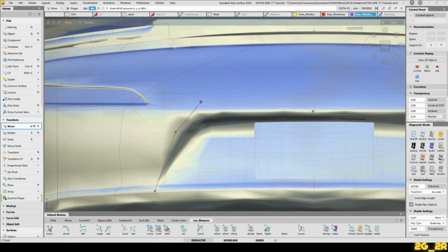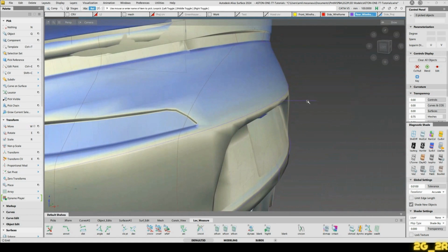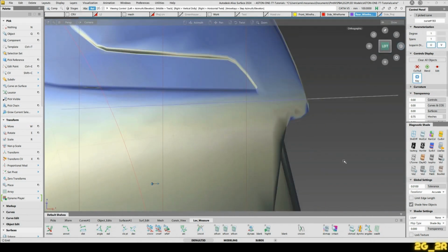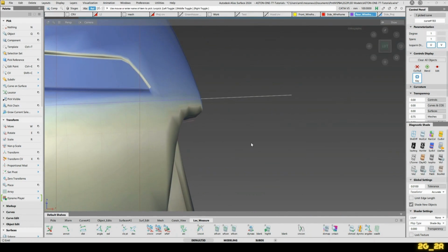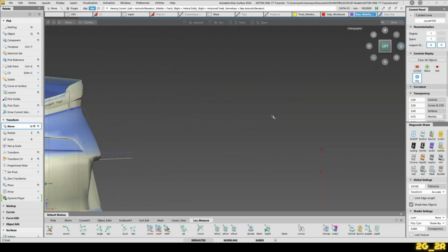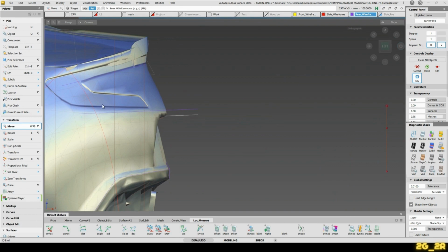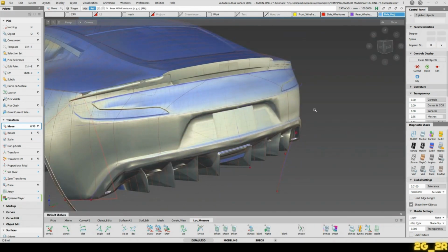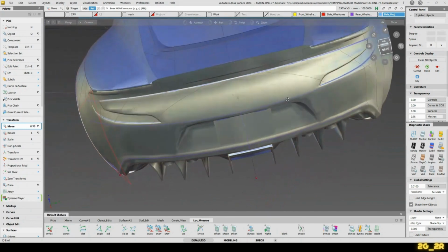I'll run this line parallel to that one, so I don't necessarily need one, but I could also take that line that's defining the plane on the side view, copy paste it, move it down to here. Let's see, somewhere around there. I'll get that onto this side projection, because it will become a side projection onto this surface across Y0 that we're going to generate.